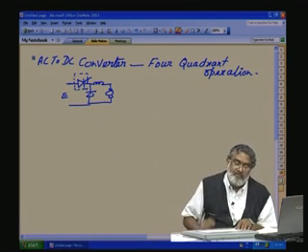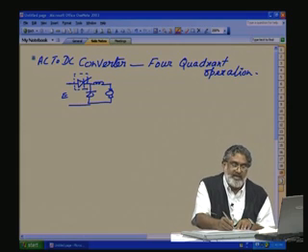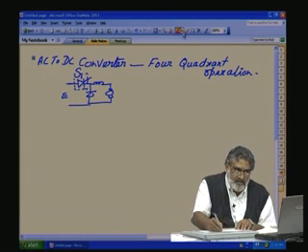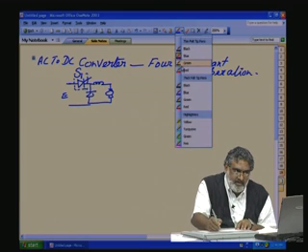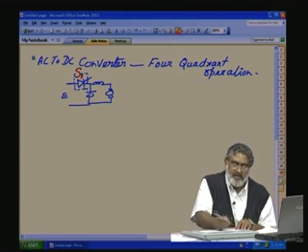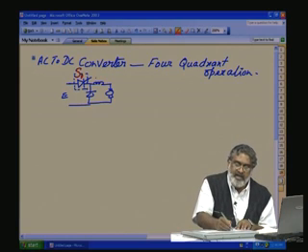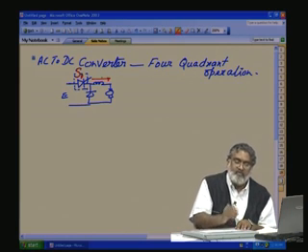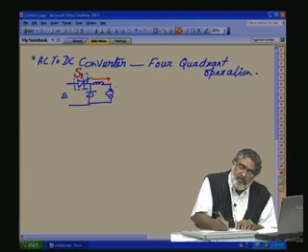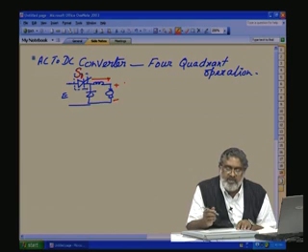Here, if you see, because of this main thyristor S1, the load current can conduct only in one direction. Okay. That means this output voltage can vary from 0 to positive only, and current in only one direction.